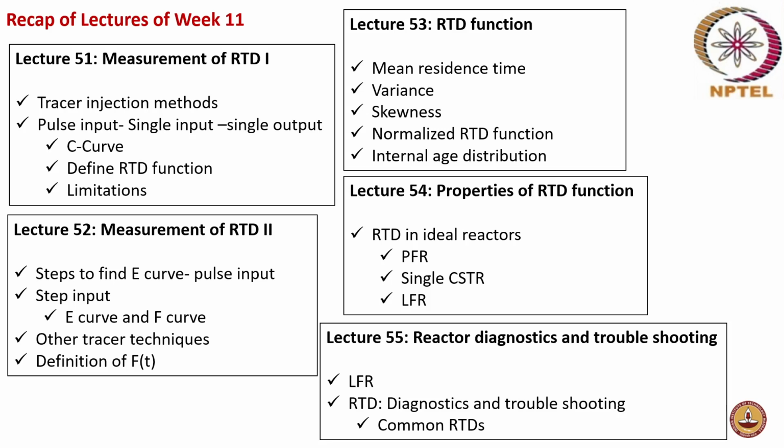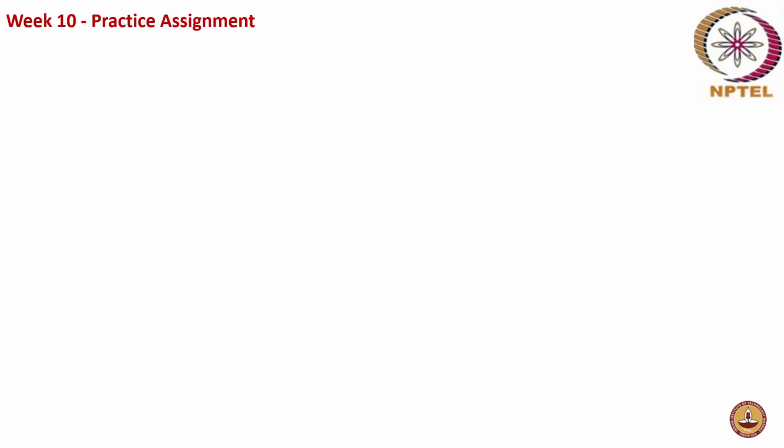And the final lecture for the week was on reactor diagnostics and troubleshooting. In this lecture, there was a continuation of the discussion on laminar flow reactor, and then the RTD diagnostics and troubleshooting was introduced, where common RTDs, that is the residence time distribution function for common reactors like a plug flow reactor, CSTR, and packed bed reactor, were all discussed. Now, let's get on to the week 10 practice assignment session.